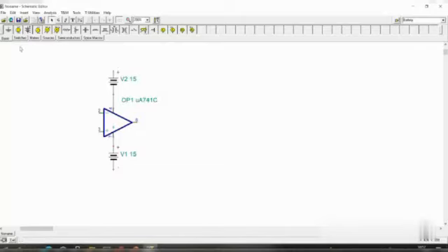So what you can do is take a ground, from the basic group icon, you will get a ground. This is ground. Even when you click here it will show ground. So what I am going to do is connect this point to ground, because the other point of the supply should be grounded, then only the 7th pin will get 15 volt. Okay, so this also should be grounded. That means here we are connecting it like this, to ground.